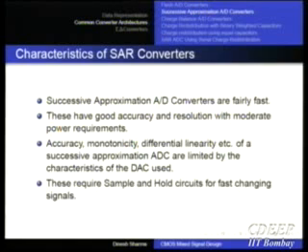So what are the characteristics? They are fairly fast, about an order of magnitude slower than flash. But now the complexity increases only linearly. That means the register has to be 1 bit higher and the DAC has to be a bit higher. I am assuming that I have not quietly swept the complexity into the DAC. We did say that the DAC will become complex, and we are assuming that the DAC responds immediately. So we have to go back and examine that carefully.